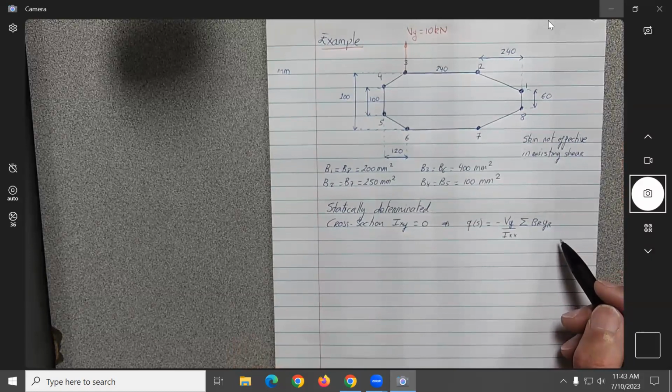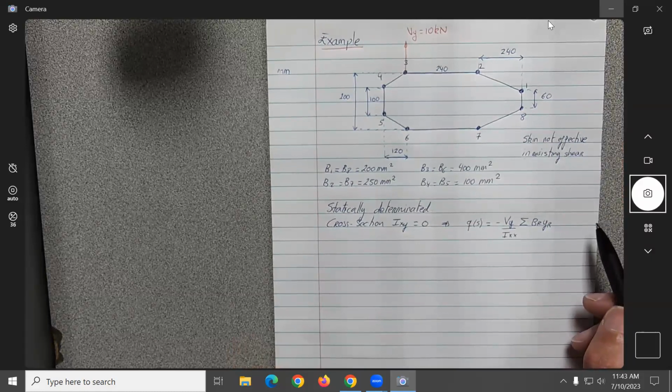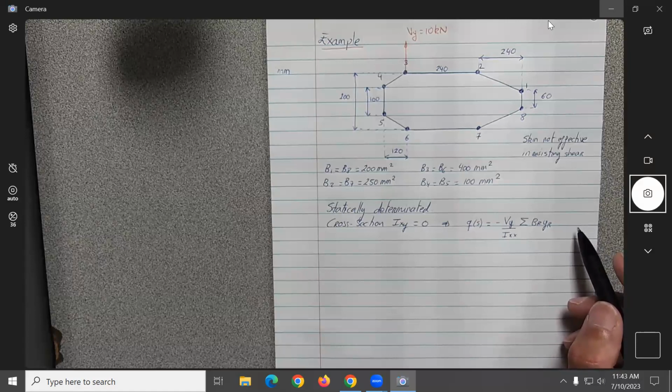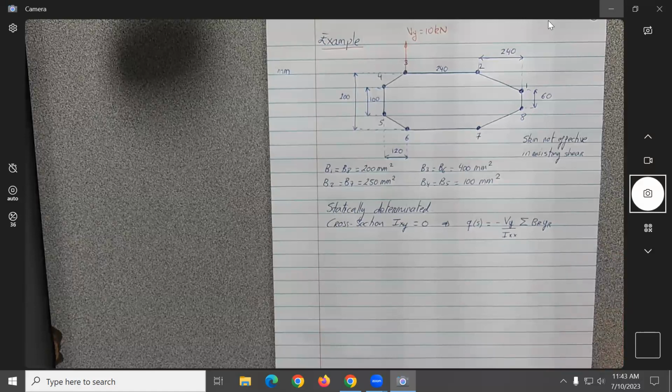Yes, a question. So I remember what it was from the homework. This is when we have a negative Vy over Ixx, and since we have no Ixy, it almost goes out. For the homework, since we have Ixx, Iyy, and Ixy, would the bottom value be Iyy times Ixx minus Ixy squared? Correct. That's why they use math, instead of killing yourself. So this is the question.